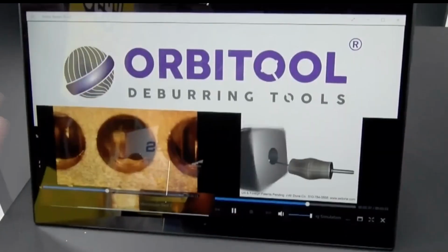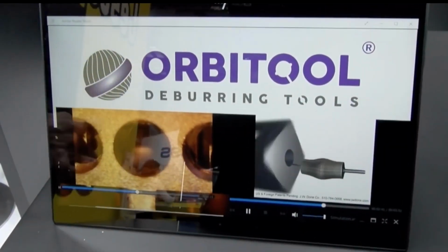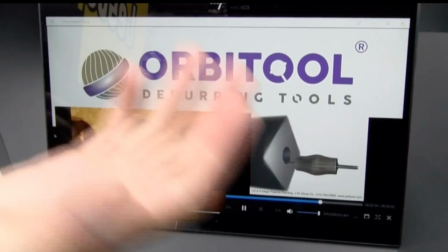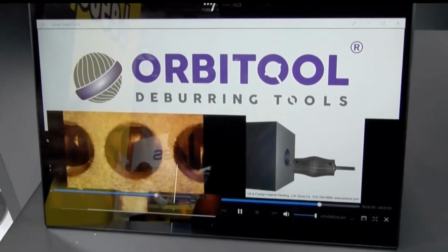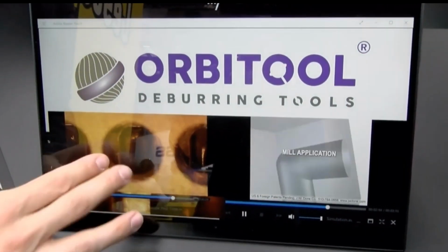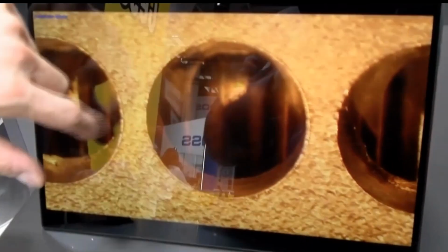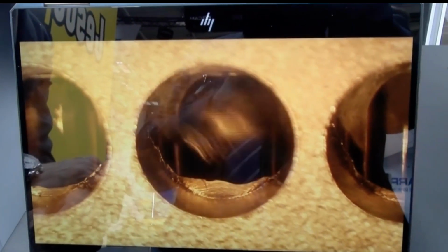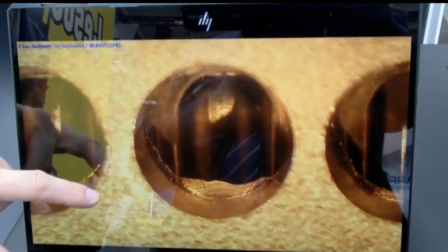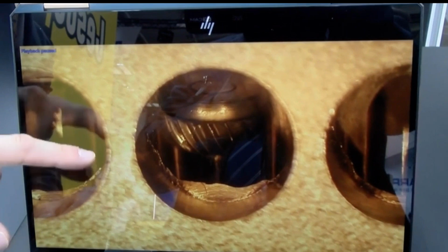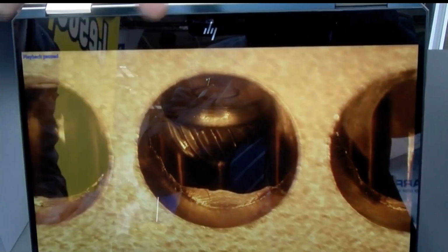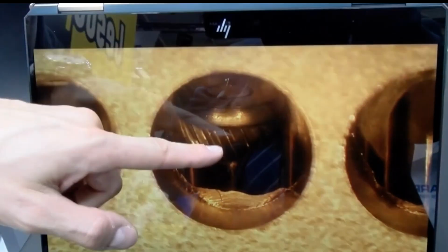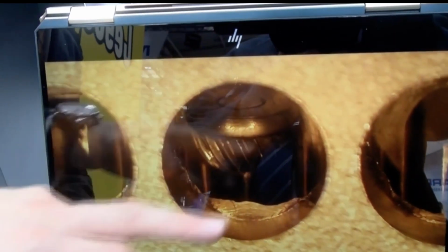You can use the tool manually in essentially a rotary grinder type setting, or you can use it on a CNC machine, either a lathe or a CNC mill. So here in a manual setting, we have essentially a 90-degree elbow with a cross hole burr at the intersection of those two holes. The cutter comes in, and we'll pause it for a moment. The protective ring is what's going to protect all of the wall surfaces, and the carbide burr will remove material only at this intersection edge.